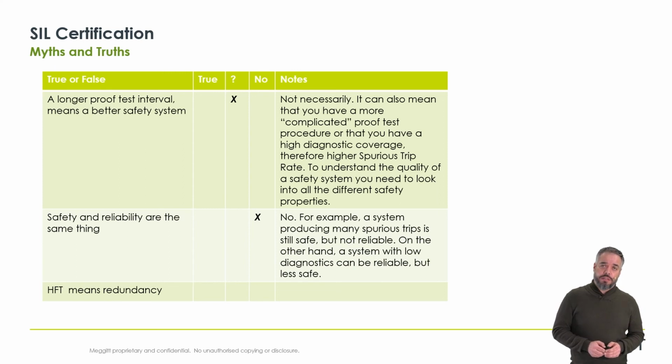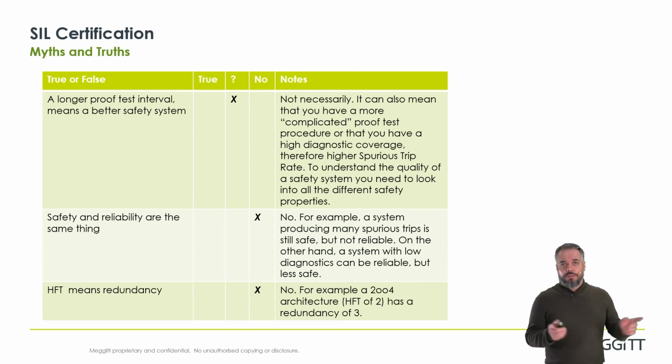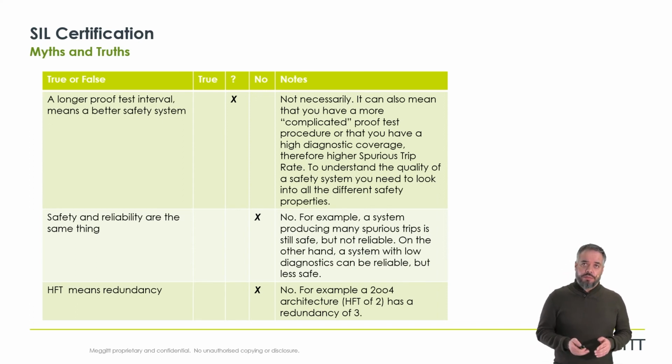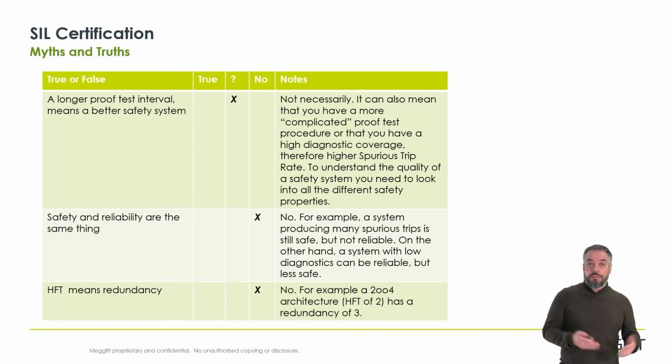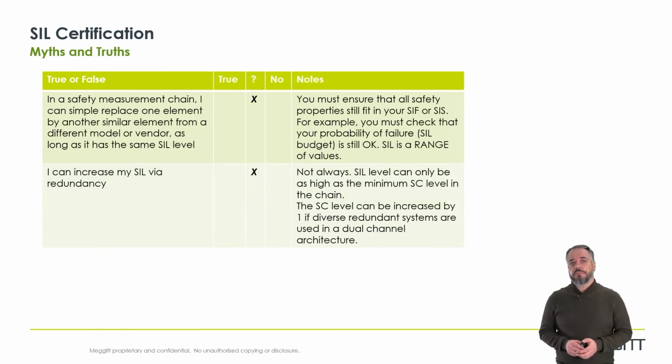HFT means redundancy? No. If you take the example of a 2 out of 4 architecture, you will have HFT of 2, but the redundancy, in fact, will be 3.